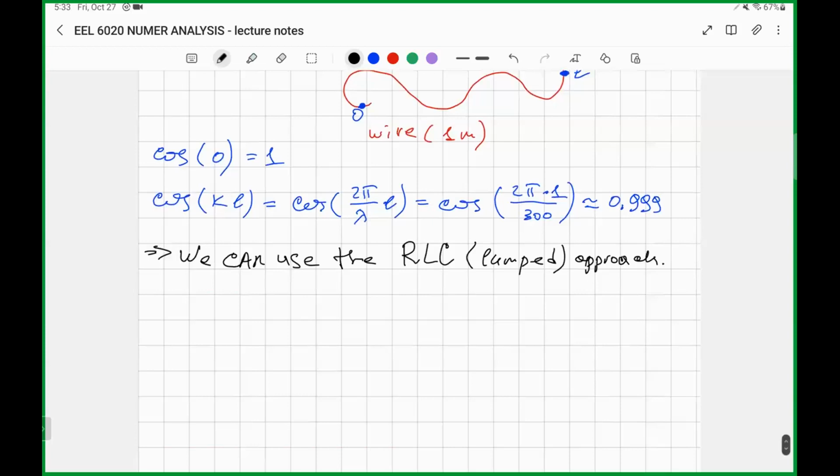Of course, if you go higher in frequency, for example to the gigahertz range, where the typical wavelength is around 1 centimeter or 3 centimeters, that's already comparable with the size of a capacitor. At such a high frequency, a capacitor doesn't work as a capacitor.